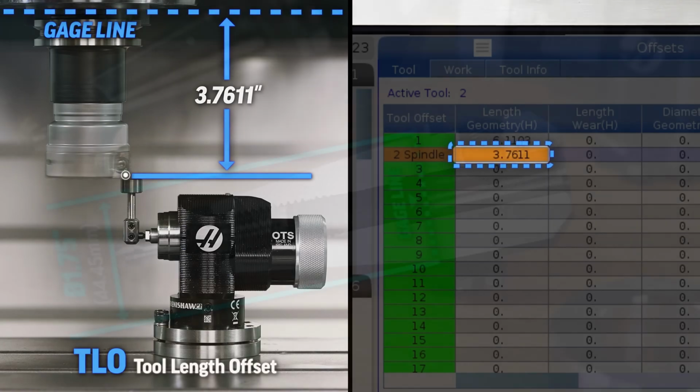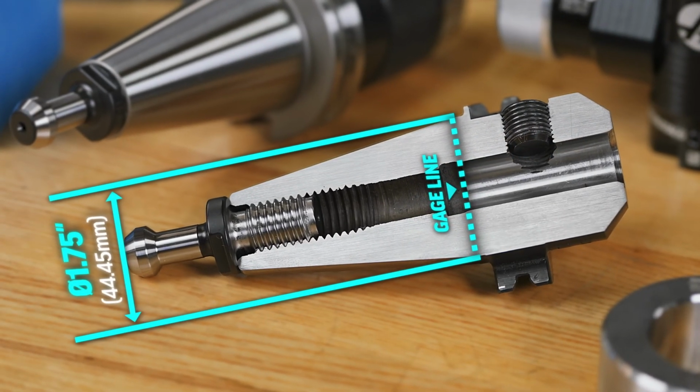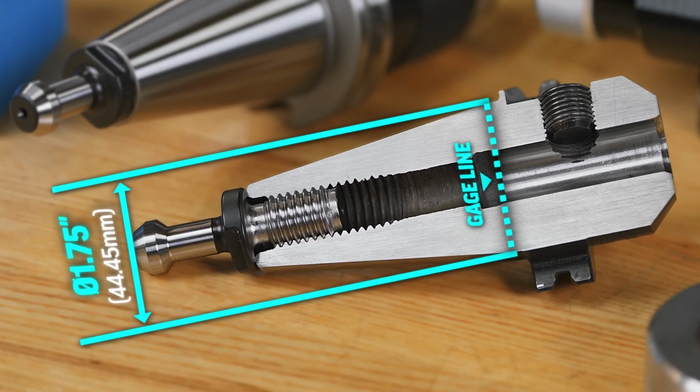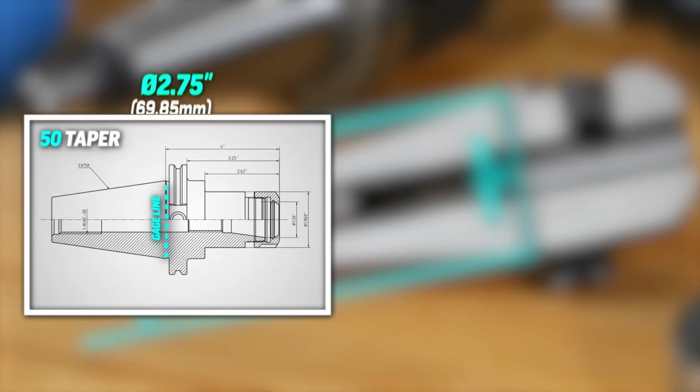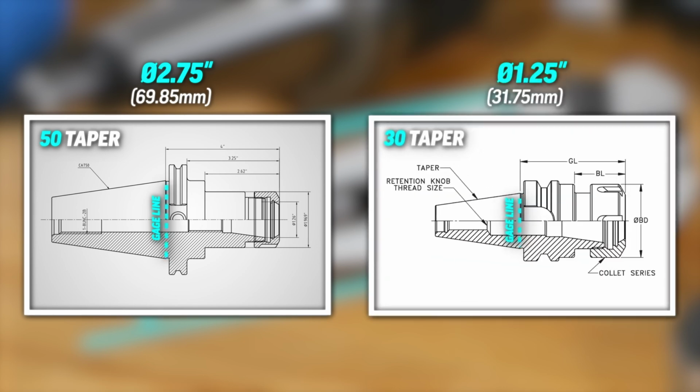This is a 40 taper machine, so our gauge line is at 1.75 inch, 44.45 millimeters in diameter. For a 50 taper tool, it is at 2.75 inches, or 69.85 millimeters. And on a 30 taper machine, our gauge line is at 1.25 inches, or 31.75 millimeter gauge diameter.